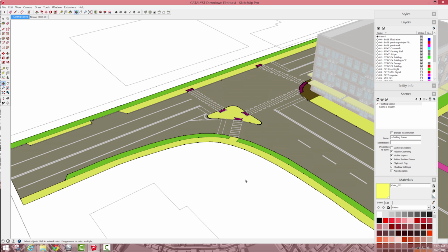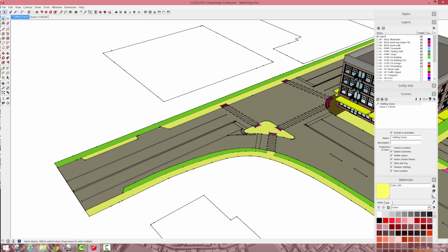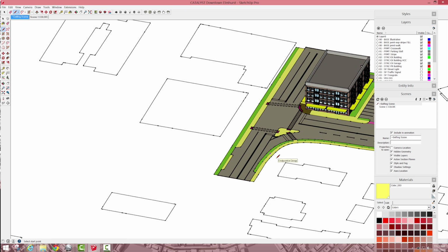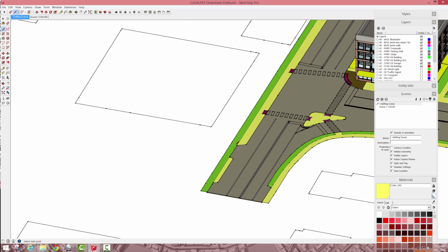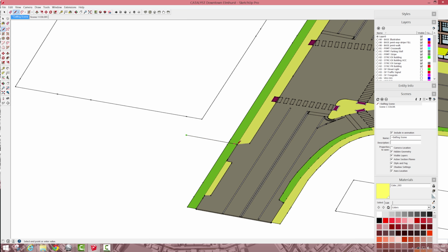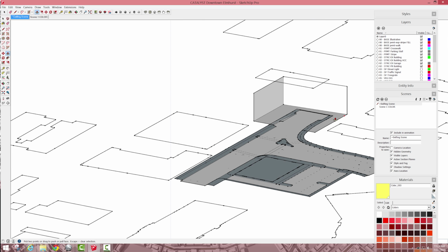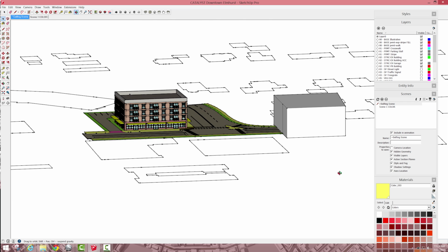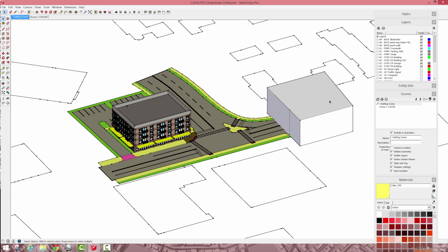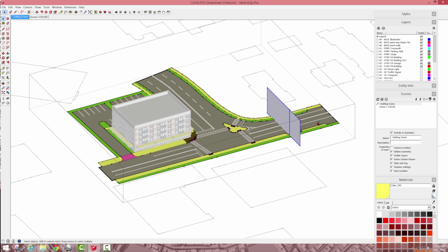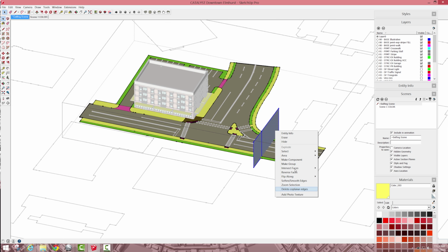Since these are now on 2 different planes, what I normally do is, outside the model, I also don't work in 3D mode, so I normally toggle. V is toggle parallel and perspective for me. I find it difficult to work in just the 3D view. So if I push this up, pull it down, I'm going to paste into place and intersect with model.